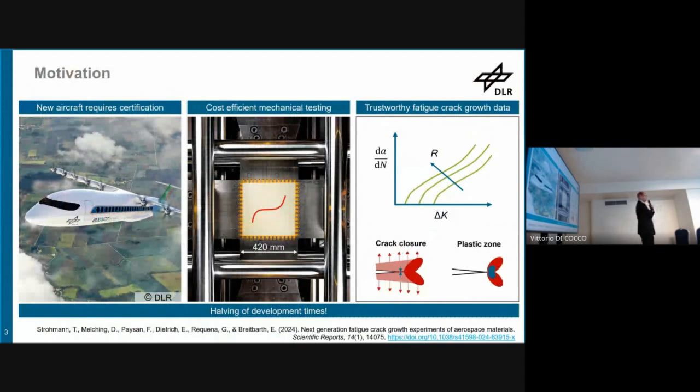If we think about bringing a new aircraft into service, we need to perform a lot of tests to ensure a safe operation when it's in service, and therefore we need to perform a lot of physical tests. Starting at fatigue crack growth tests at component level, with a specimen with the size of a sheet of paper, and ending with full-scale tests by testing a whole aircraft. And of course, this requires a lot of time and money, and it takes very long.